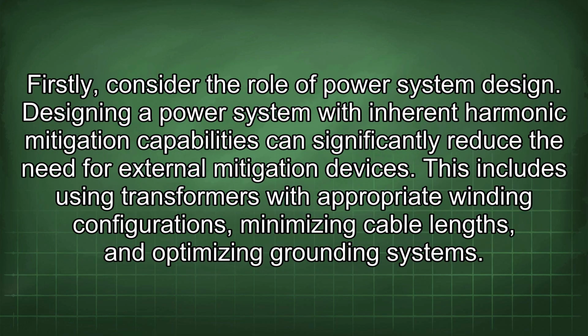Firstly, consider the role of power system design. Designing a power system with inherent harmonic mitigation capabilities can significantly reduce the need for external mitigation devices. This includes using transformers with appropriate winding configurations, minimizing cable lengths, and optimizing grounding systems.